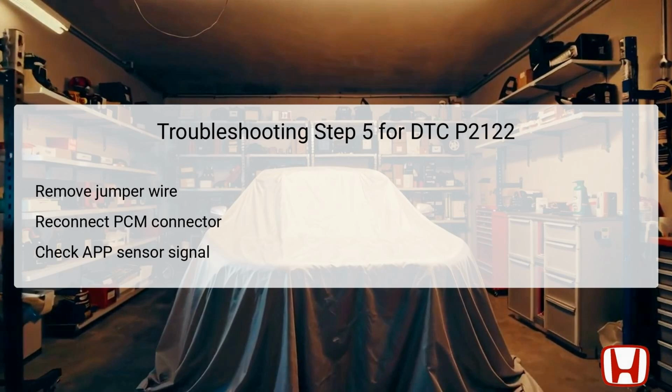In this step, it's essential to remove the jumper wire you set up in the previous step to ensure proper system operation. After removing it, reconnect the PCM connector A. You will then need to create another jumper between pin number 4 and pin number 6 of the APP sensor 6P connector. With these connections finalized, turn the vehicle back to the on mode and use the HDS tool to check the APP sensor output voltage again.